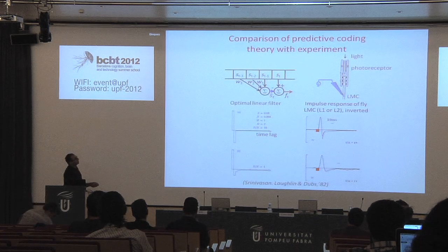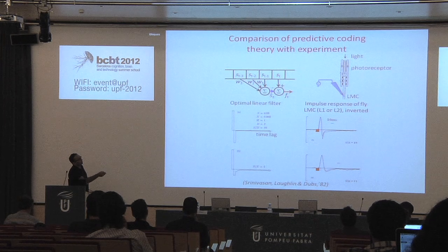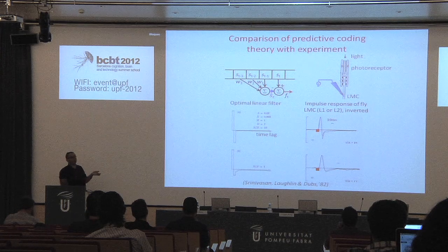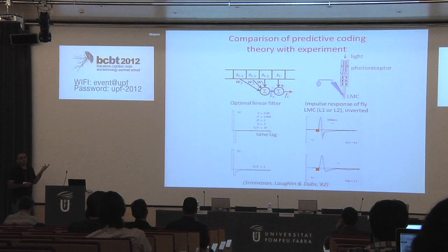Consider, for example, the case when you get white noise input to the system, and it's trying to predict, so it takes the previous value, but what you actually get is uncorrelated with that prediction. Then what will happen is that it will actually increase the dynamic range of the transmitted signal.